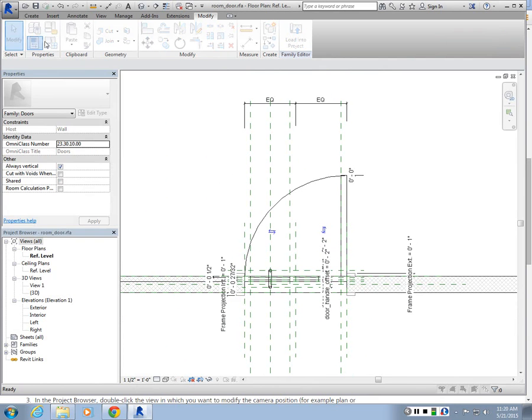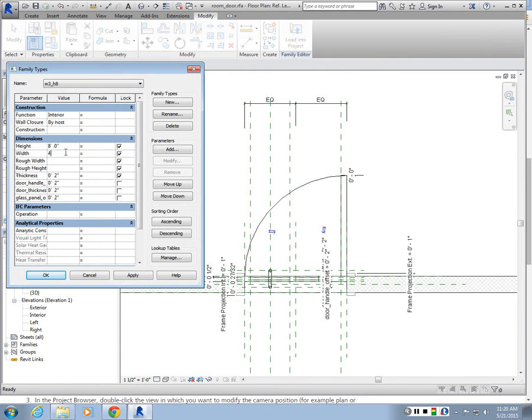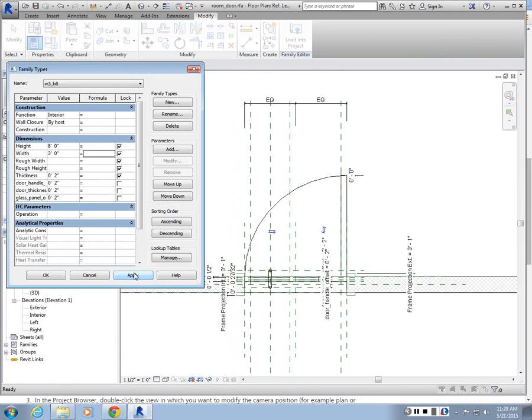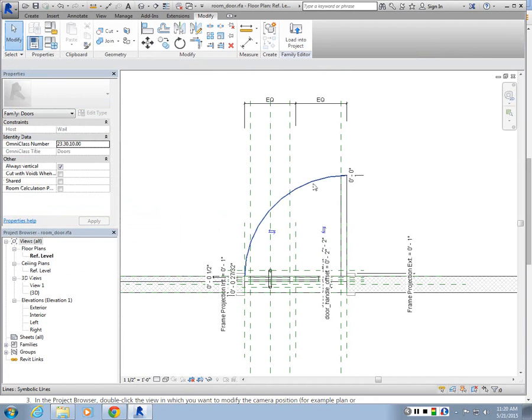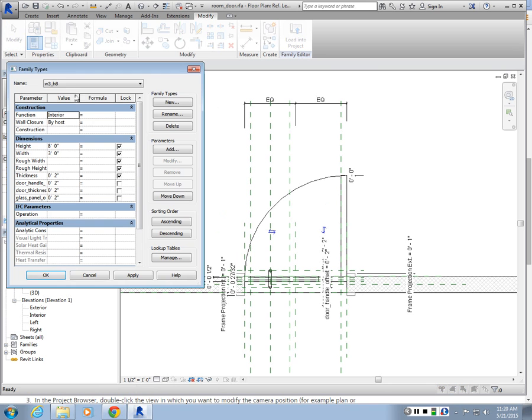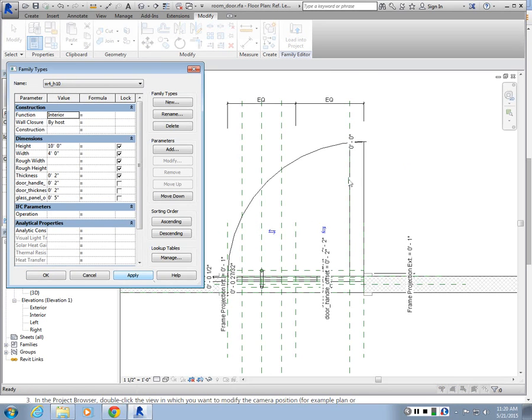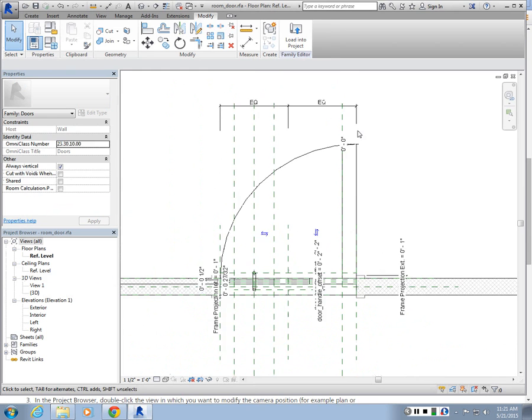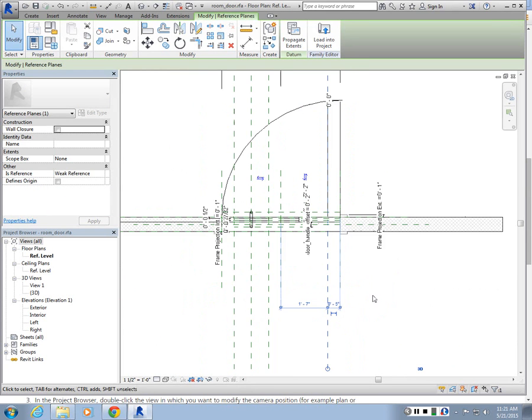And if I go to type properties and stretch it, let's see if it's going to work. It stretches the two-dimensional drawing as well, according to the variation I had, which is nice, right? Okay? So it's just basically drafting simple lines, and then they become adaptive as well. So when you stretch with the variations, they do stretch as well. Now this guy though gets another thickness that we may not want. And this guy, let me see.